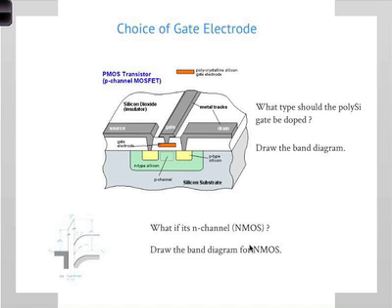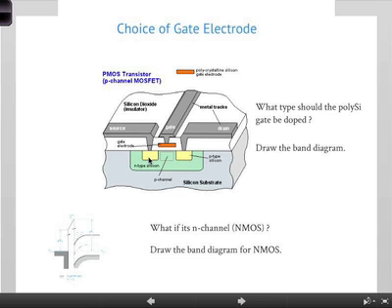So that's N-type silicon, P-type. Yes. Okay, just want to make sure. N-type what? Sorry, I didn't hear you. It's a PMOS transistor. This is opposite to what you saw before. So look at the body, it's N-type, as opposed to the body that was P-type. Yes. It's the opposite of what we saw.